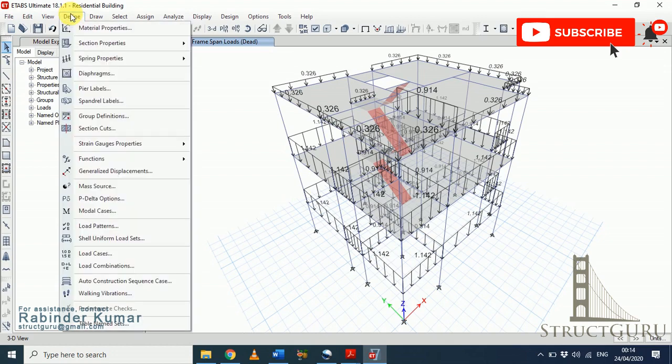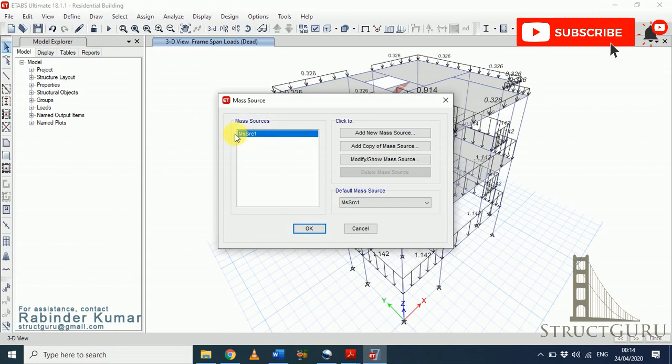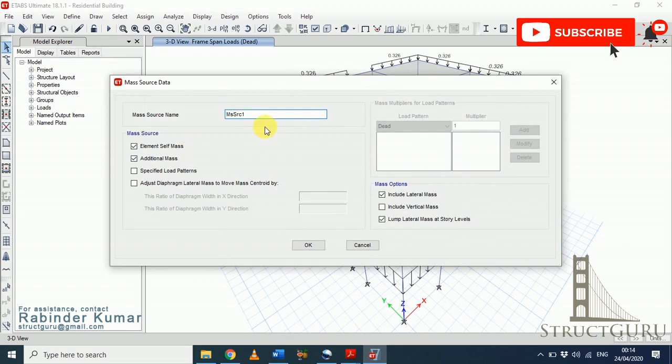Go to the Define menu, click Mass Source. As you can see, ETABS by default has defined a mass source, but we have to modify the parameters in it. Go to Modify/Show Mass Source. If you want to change the name of the mass source, you can do so by typing a name here. Let's type Lateral.